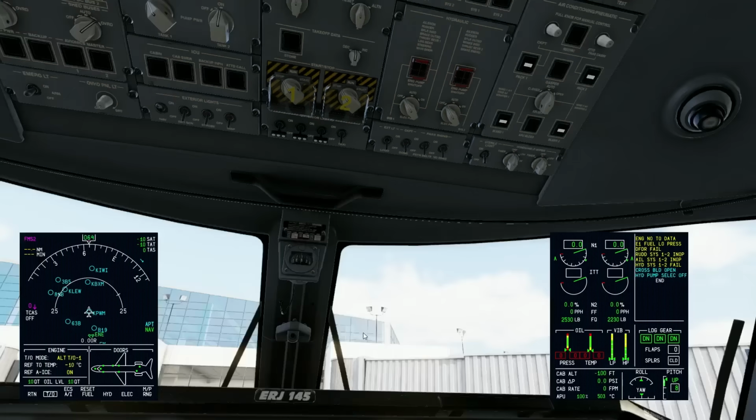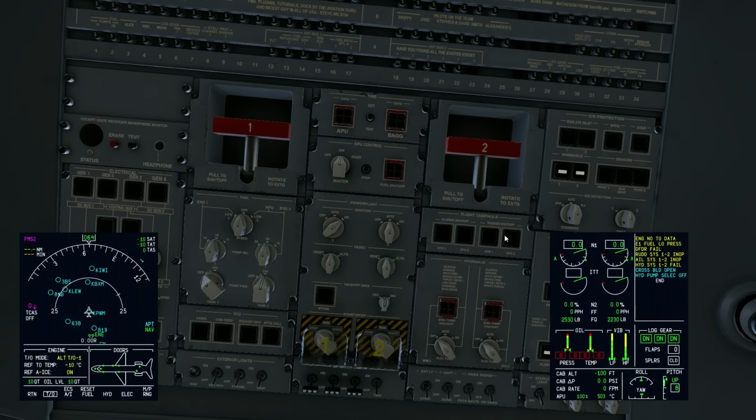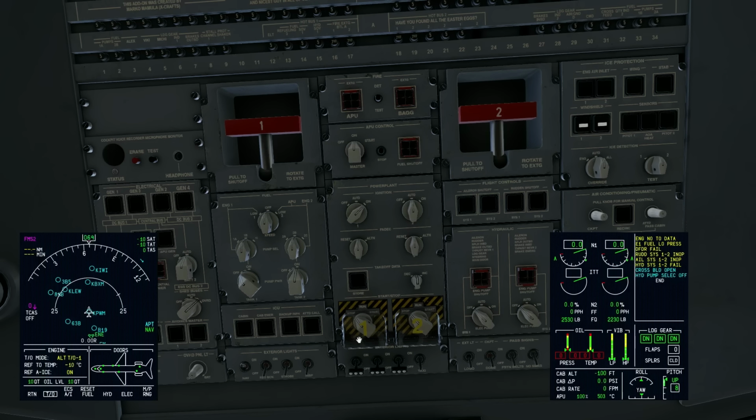So we always make sure that the thrust levers are in idle, and then we also always make sure that our engine indications are actually showing. Remember, this is a request, this is the truth. So a big one to look for is fuel flow, because a shutdown engine is going to have no fuel flow, obviously, because it's not asking for any fuel. But a running engine might, so when you turn those to stop, just make sure, and same when you turn them to start. We'll go over starting the engine in a couple minutes when we do it. But when we start the engine as well, make sure that N2's actually rotating. Don't be sitting there just waiting for the engine to start. Actually verify that you did send a start command.